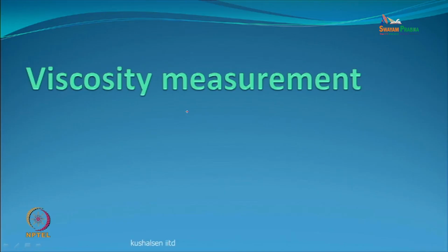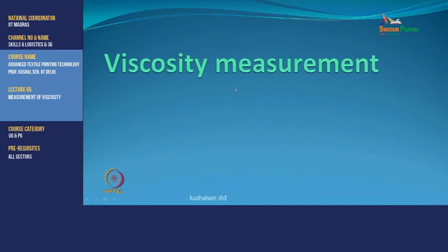It is like when you talk about the crystallinity of a polymer, you say how did you measure? Say I used a wide angle X-ray diffractometer, very good. Another one can say I used a DSC to measure the crystallinity, or density to measure crystallinity. You have to say, well, this is density crystallinity, this is X-ray crystallinity, and this is the other method that we use. So you have to talk about the method.